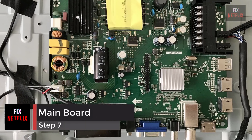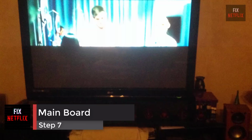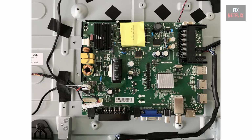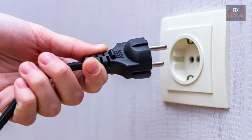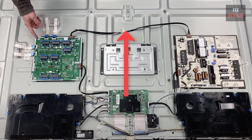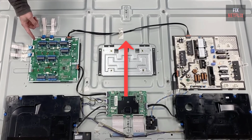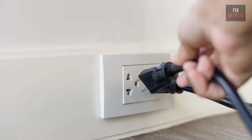Step 7. Main board. Now we check the main board to see if it is the culprit. If a problem shows up on half the screen or only a portion, it is likely the main board, rather than the T-con board. Make sure the TV is unplugged. Plug in the cable running between the power board and the main board, which was disconnected in the previous procedure. Then plug in the TV.